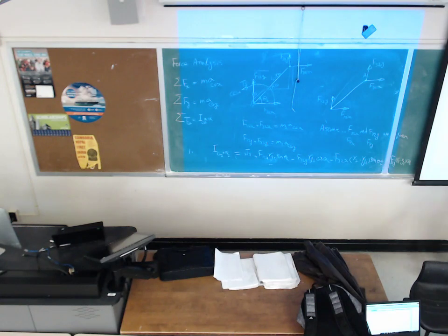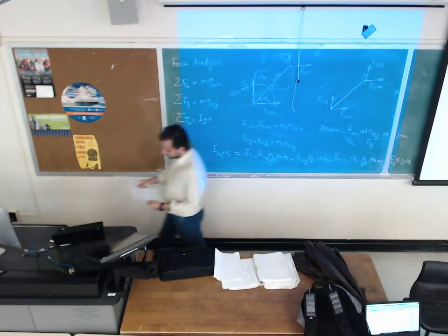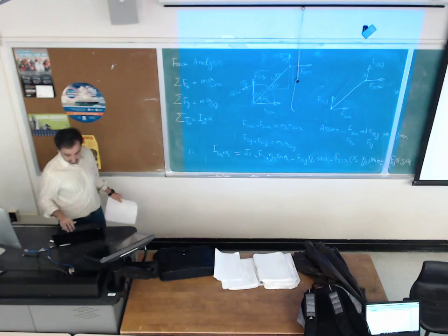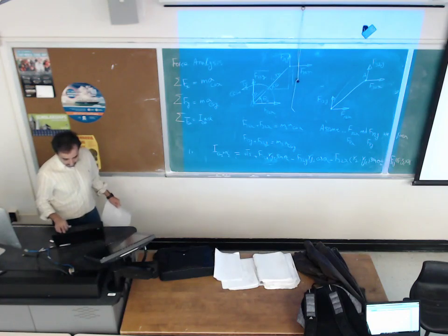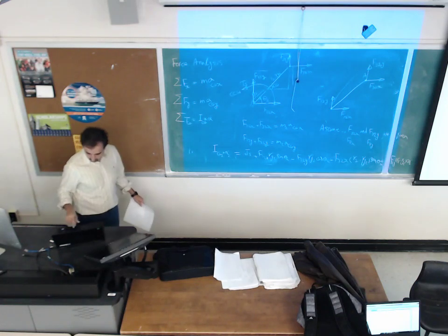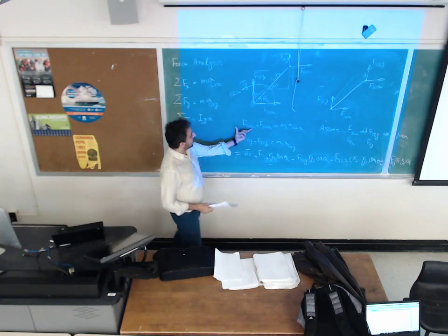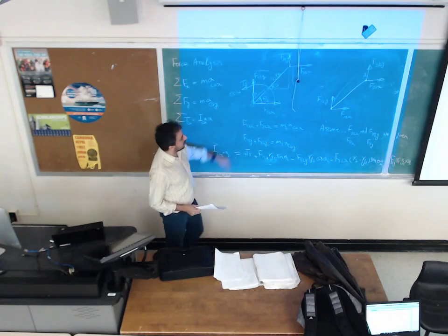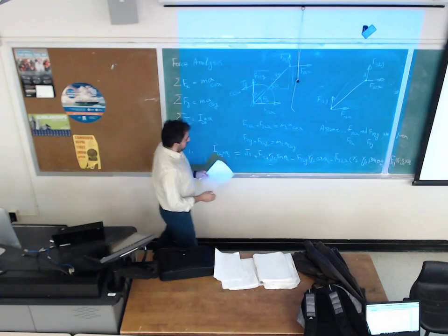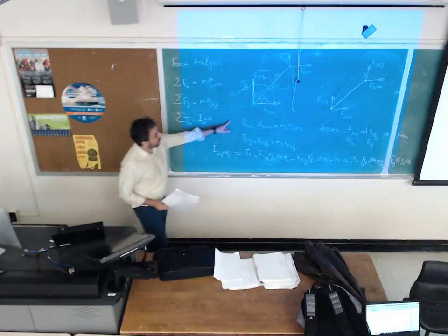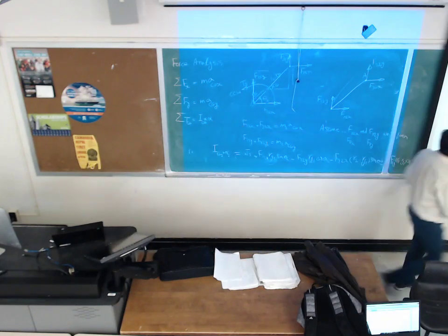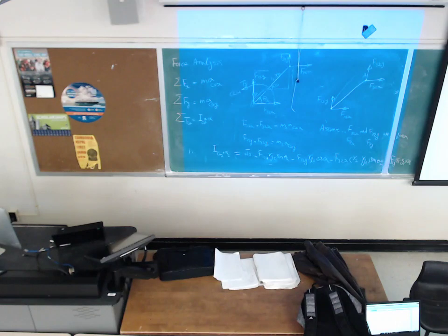So now I'm gonna rewrite these three equations in a matrix form. F12x is unknown. I'll keep it this side. F12x equals mass of link 2 times acceleration of center of gravity x minus FPx.